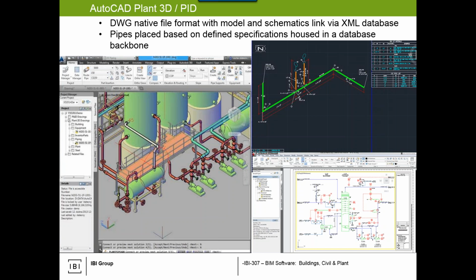So if you're a Revit user out there, imagine, we already have built-in complexities. If we're doing a heavy industrial project, or if we're given a plant model, it's going to be in a format that's either DGN from Bentley or DWG from AutoCAD, and there's still going to be a workflow on how to make sure that I can bring this information into Revit to model around and reference where needed. The thing about plants, remember from the beginning of this presentation, plant is not IFC compatible. So there's no export to IFC and import into Revit, because these are plant-based tools governed by the other ISO standard, 15926.